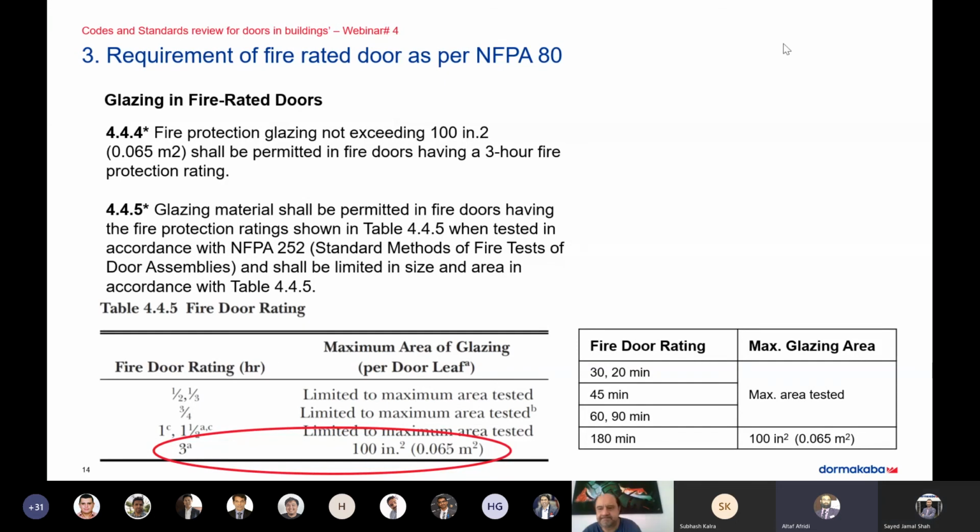So there is always an argument that it's not good for smoke or other purposes. But since, as per European standards, such a door has been tested and has passed the test successfully, if the door is already tested and certified, then yes, we can use it if the building is designed as per European standard. So this finishes all the questions in the chat box.